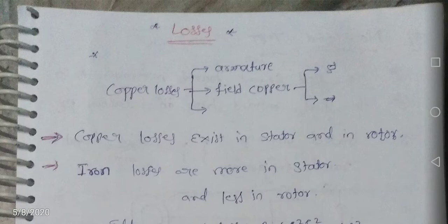So remember that in the torque slip characteristics at starting, T is inversely proportional to slip. So torque is inversely proportional to slip. So the torque slip characteristics are a rectangular hyperbola. When it is under running condition, torque slip characteristics are linear, T proportional to S.